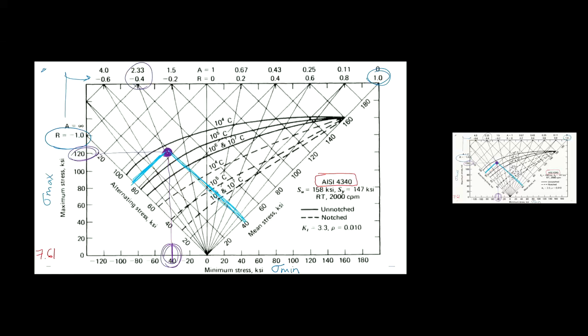Okay, so this is kind of like a master diagram. And I didn't point out maybe the most important part, which is the lifetime curves that are on here. So my big purple dot is underneath that top series, right? Normally we want to define the safe and unsafe regions on a plot like this. So this line that I'm going to highlight in red here says 10 to the 4. So that's 10,000 cycles of stress. And so I am below that.